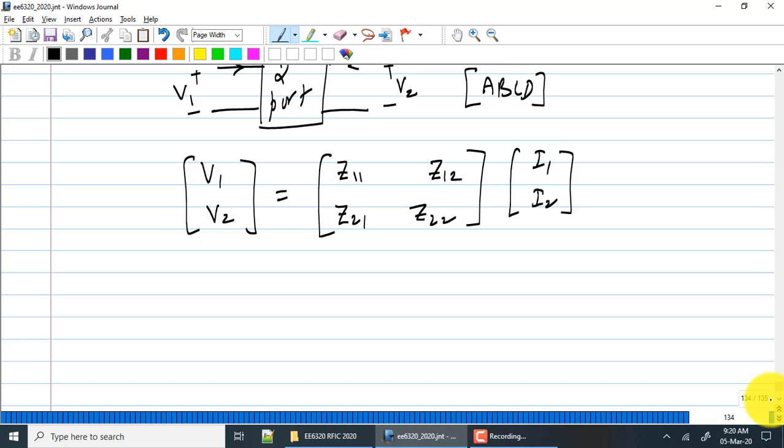I'll put it in a different way. At any node in the distributed system, the instantaneous voltage and current waves can be thought of conceptually as the sum of a wave traveling in the forward direction, let us say input is on the left and output is on the right. So in any distributed system, you can think of a forward traveling wave and a reverse traveling wave.